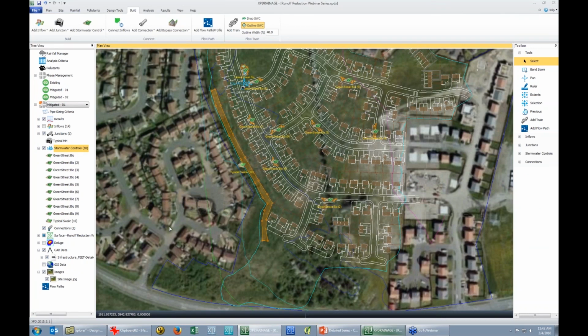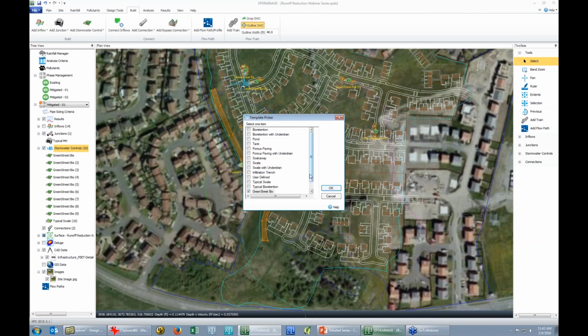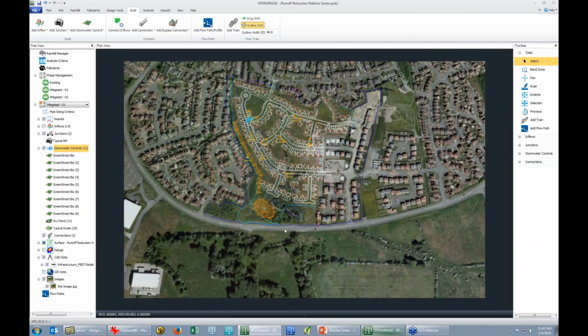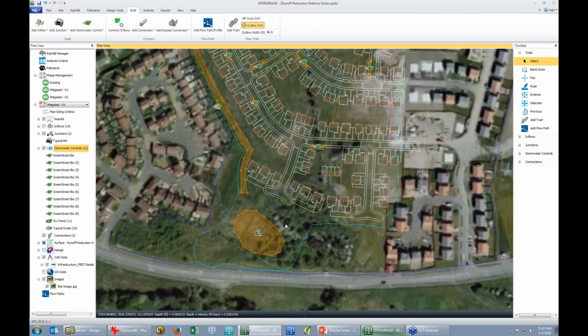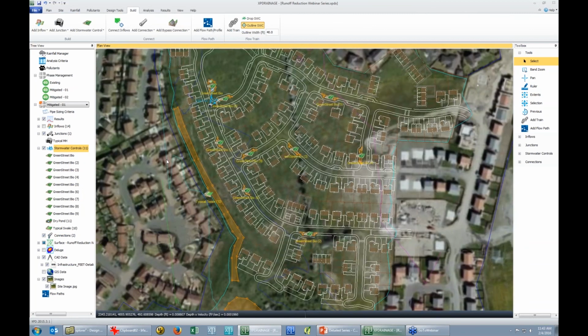And again, our pond, which we could either manually draw or again just import from this CAD file, where it's already been kind of outlined where we think it's going to start. Again, we'll talk about this more in the next webinar, but all we really need to do at this point, like this dry pond, is place where we think the treatment needs to be. Because we have some tools, some tricks, some ways we've made it easier to optimize and calibrate the system.